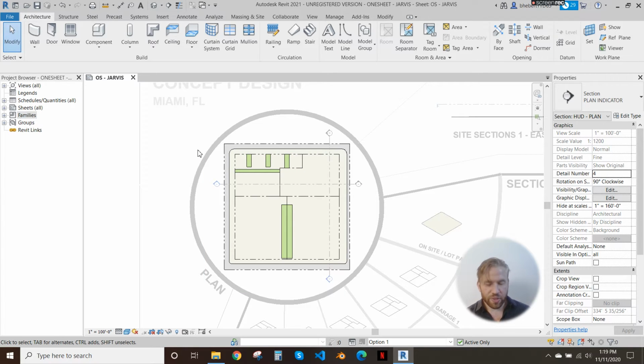So what we're going to do is we're going to use ceilings. These are pre-made custom parameters and custom family types that are all ceilings that I'm using to do building massings with. Now, the reason that I'm doing this is because ceilings are probably the easiest to work with in terms of massing. When you create thickness for these, they populate up rather than down like floors do, and so it's actually the least number of clicks, oddly enough, to get to a full massing concept.